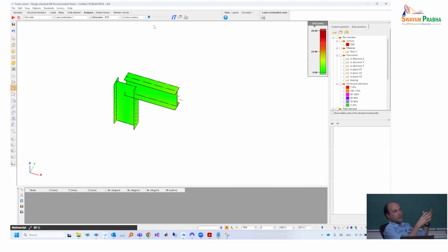It's also very important for the bending moment. Typically, all the finite element calculations assume that the Bernoulli-Navier hypothesis is valid, that the cross sections which are connected are rotating together. But imagine we have a very deep I section and a shallow I section, and you don't put any stiffener into the other element, and you apply a bending moment to this one. What is the chance that they will nicely rotate together? They will not. In traditional software we always assume there will be a smart engineer who will put in a connection which will somehow make it work, maybe some triangular stiffeners to make the transition between the deep and shallow elements more continuous. So that's a connection problem.